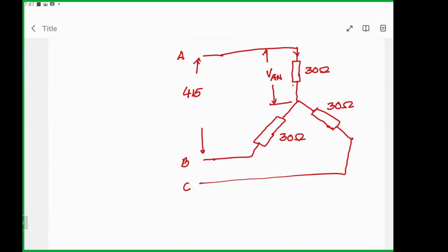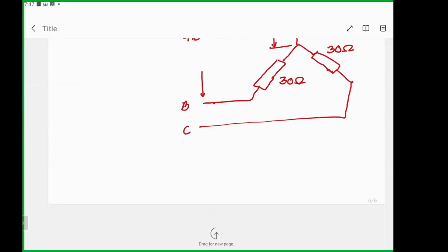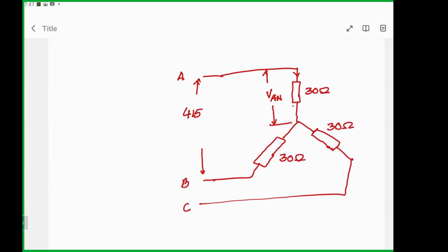and the current. So if it is a star connection, then we can do this using a simple relationship. We know VAN would be equal to VL divided by square root of 3. So we can just write down 415, and we'll consider this angle is 0 degree, and then square root of 3. So what is the value you have found?